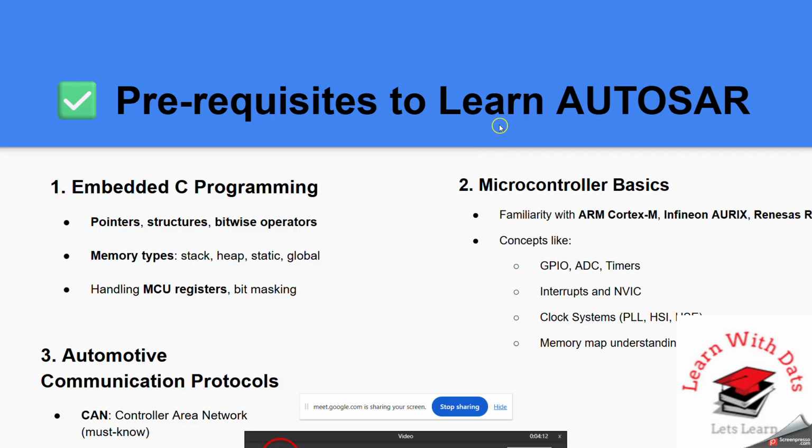Also, in terms of diagnostics, we are always pointing to data with the help of pointers. There will also be structures, like let's say you want to read some vehicle parameters. In vehicle parameters, there can be various parameters, so for that you need structures. You also need bitwise operator information. Let's say you want to see the sensor status, whether it is on or off, or do some output control, like turn on the actuator or the sensor, or turn on the light, or read the sensor information from the car. All those things will need structures and bitwise operators.